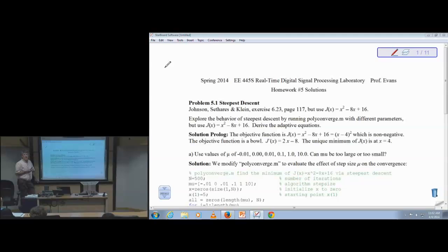Carrier frequency, which we deal with a little bit later, the receiver has to figure out what that is, that the transmitter is using, both the carrier frequency and the phase. So as long as we come up with an objective, some measure of what we'd like to optimize, then we can come up with an adaptive framework that will make progress in updating our equalizer filter coefficients or tracking loop or phase lock loop, whatever it is, to get a better performance in the application.